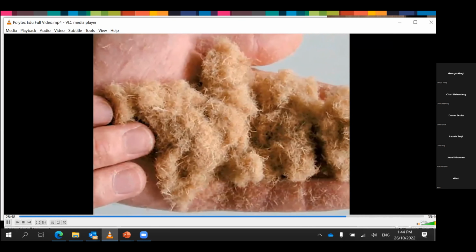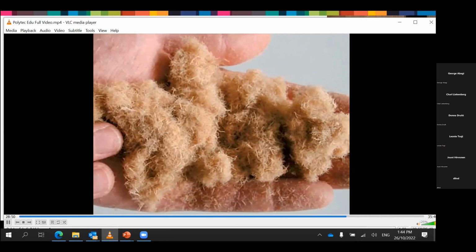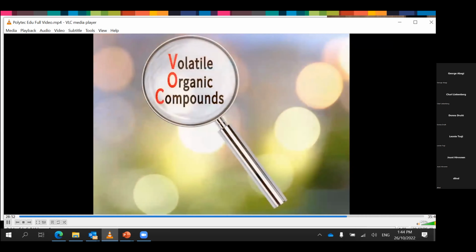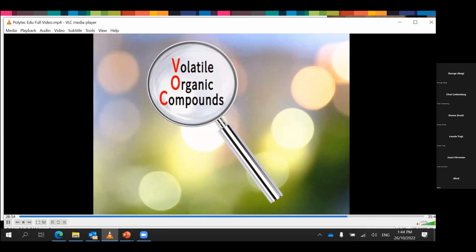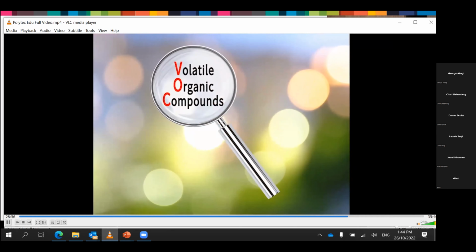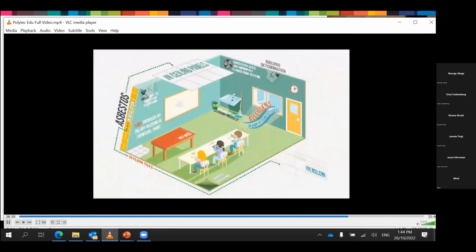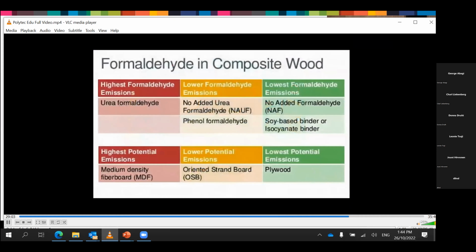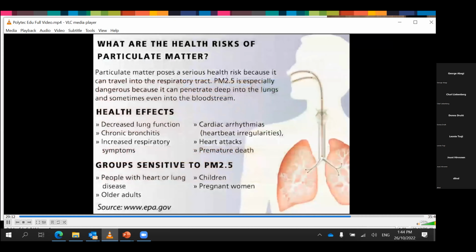As we have explored briefly, the two most popular core materials for the construction of joinery, another point to consider is the volatile organic compounds, VOCs. Concerns that were brought to the attention of the Australian public in the early 1990s were formaldehyde emissions. Different levels of formaldehyde are found in most materials. There are products that have much safer levels of off-gassing. These are available and are fit for purpose, but are unfortunately not often specified unless specifically requested.